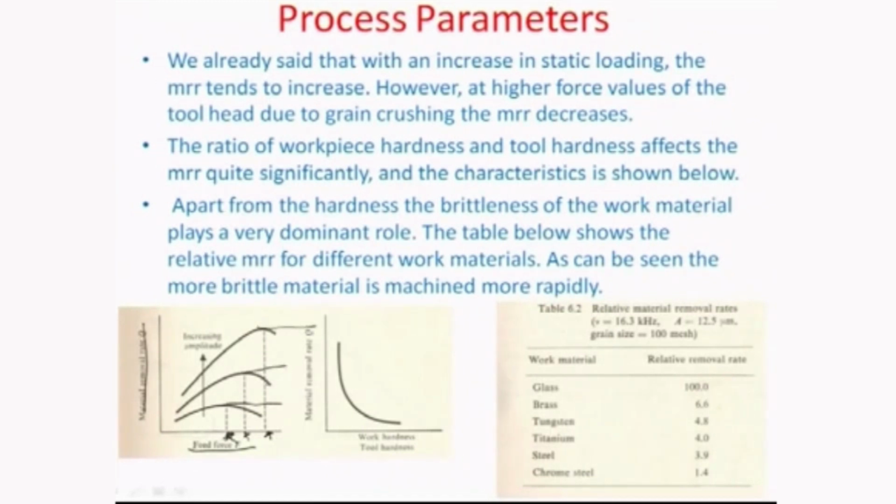That is probably obvious because the gap between the tool and the workpiece is more. It is important to see that if the gap is more, then the critical feed force needed for this grain crushing effect would actually be higher, because the tool has a higher relaxation time for going from the surface all the way towards the other extremity.